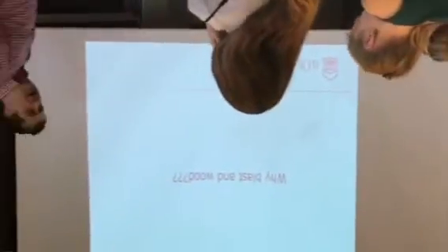Now, the first thing that comes to your mind is, if I'm possibly going to be exposed to blast, why would I build my building out of timber? It doesn't make sense, right? Timber is a weak material. Timber doesn't really present itself as a blast-resisting material. Well, there are certain things in timber that are really bad from a blast perspective, and that is it's lightweight, and it's a brittle material. So these two things really work against it.